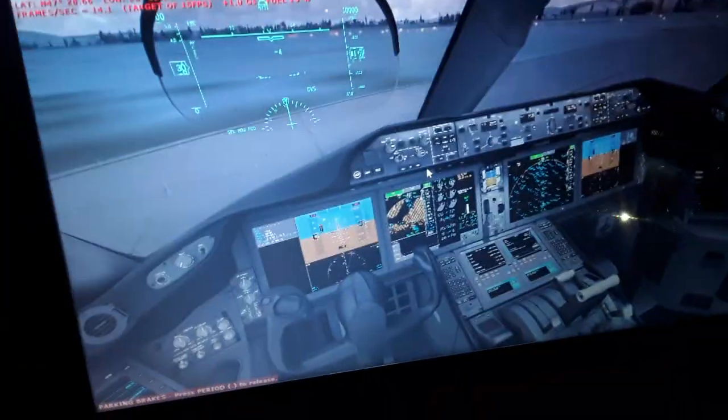So the flight management computer is going to calculate the center of gravity of the aircraft for takeoff. Also the mean aerodynamic chord position, which is 23% of the mean aerodynamic chord, and also where the maximum aerodynamic lift occurs in the forward wing, so the stall will begin in flight. So you need to monitor here in the primary flight display.